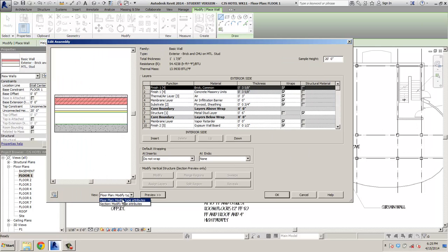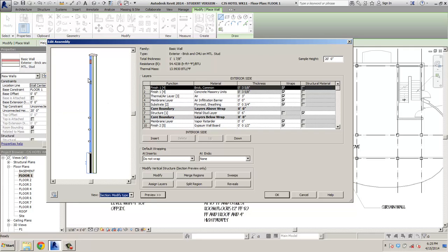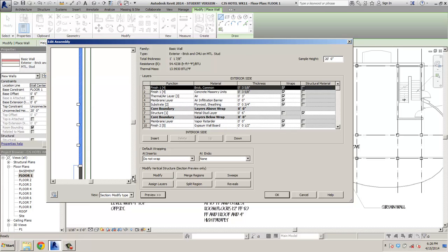We're going to look at the section view through this wall. If we were to take a section through, at the top, see if I can zoom in here a little bit, we have a concrete parapet cap. We have brick, that's this blue on the outside. This red is a soldier course of brick. It means they're standing on end. Down here in the bottom we have some recesses in the brick.